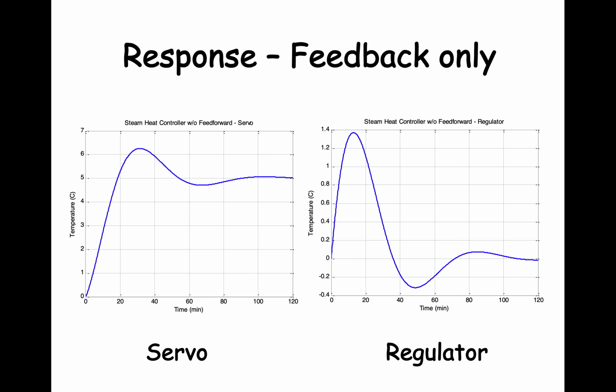For the servo problem, the set point was changed by 5 degrees C, and for the regulator problem, the inlet water temperature was increased by 5 degrees C. And it takes over 60 minutes for the response to settle down.